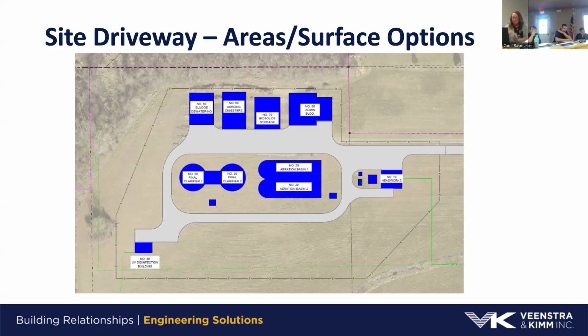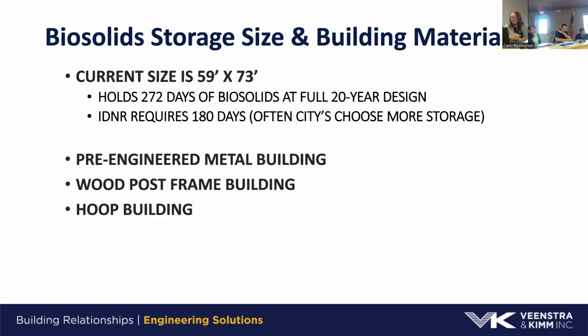The next item on the list to discuss with you is the biosolid storage size and the building material. The current size of the biosolid storage is 59 feet by 73 feet, which is what's shown on that drawing that you have, the rendering. It's sized to hold 272 days of biosolids at the full 20-year design. Keep in mind that the existing facility is about a third of the size of the future facility.